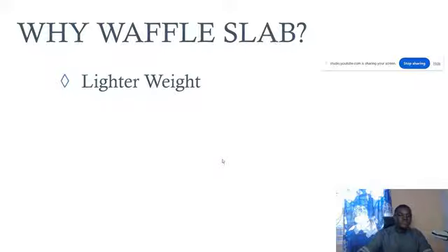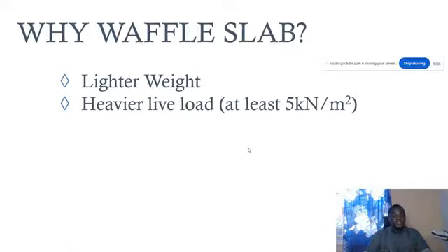Then another reason why waffle slab can be considered is that it is suitable to support heavier loads. Waffle slab technically is provided where we have a longer span and the live load we need to take in that kind of situation is high or heavy. From theory, they will tell you at least 5 kilonewton per meter square.